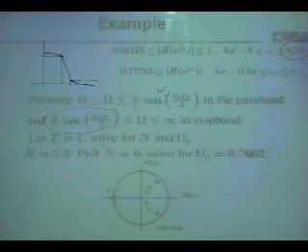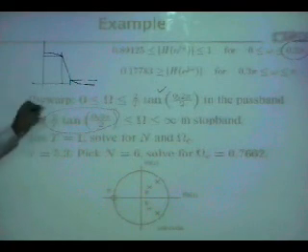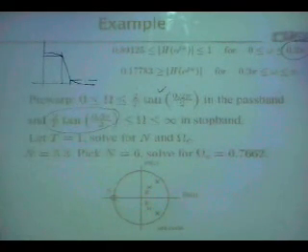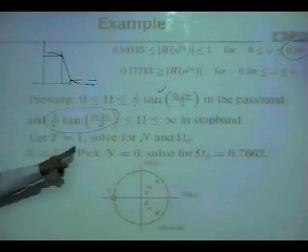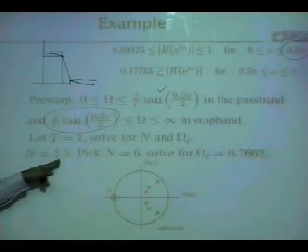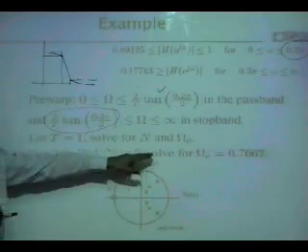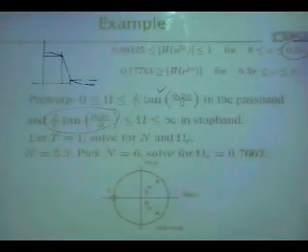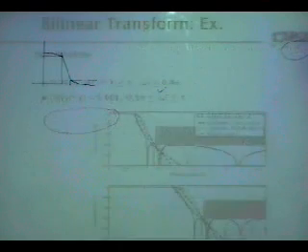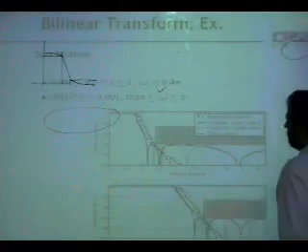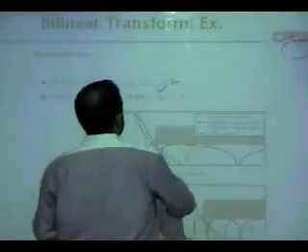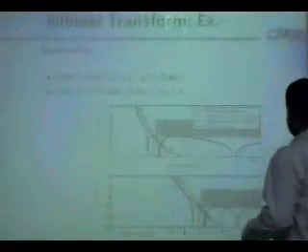If you are designing a Butterworth filter, it will be a monotonically decreasing function of omega. So knowing this, you get n is equal to 5.3, you bring it to 6, find out a value of omega of C. So it is this. So knowing this, now you design a filter and then use the bilinear transformation to convert that to H of Z.